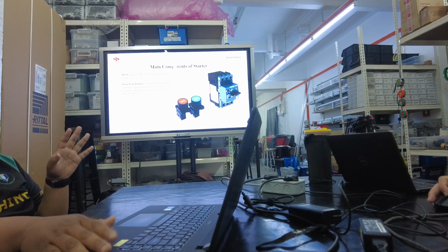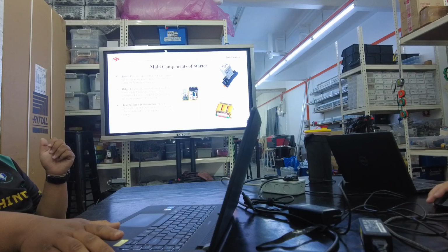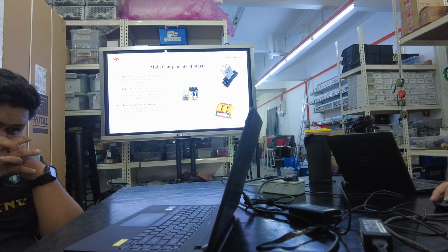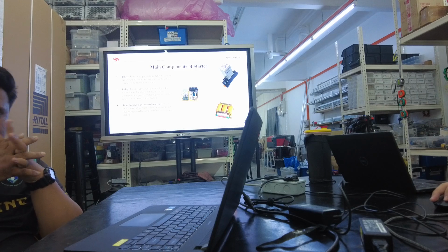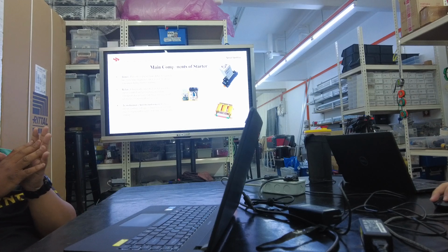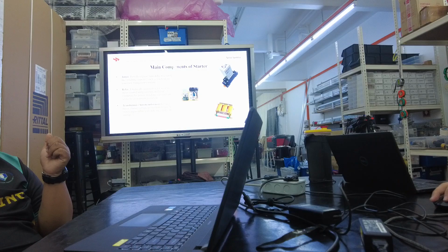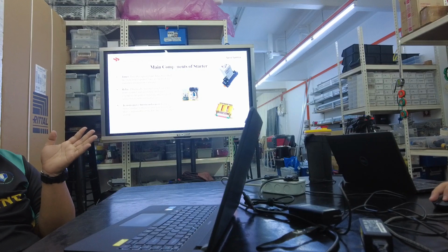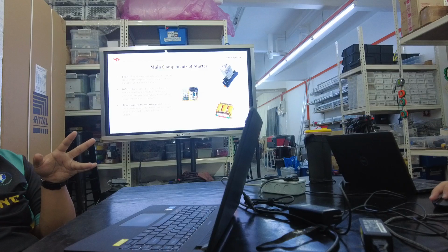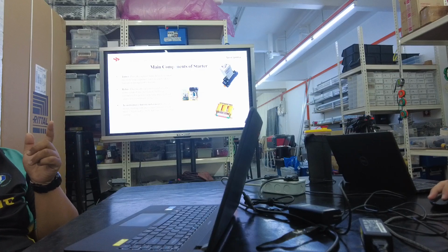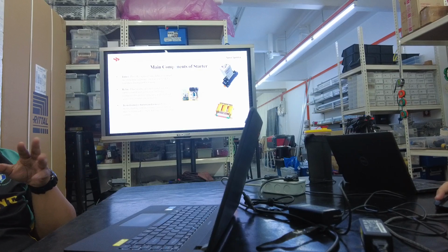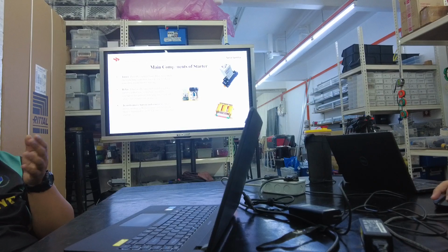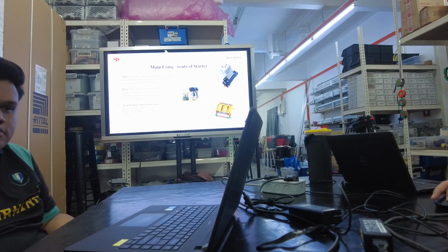Then we have the timer for the control. It provides a way to set a timer to delay the control circuit. For example, in the star delta starter, the control transitions from star to delta by de-energizing the star contactor and energizing the delta contactor after the motor has accelerated to a suitable speed.